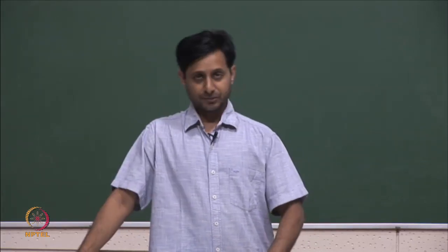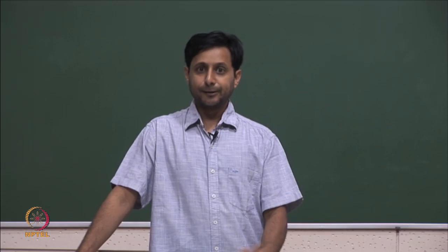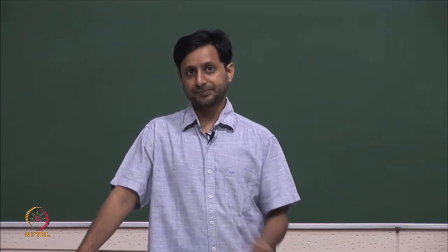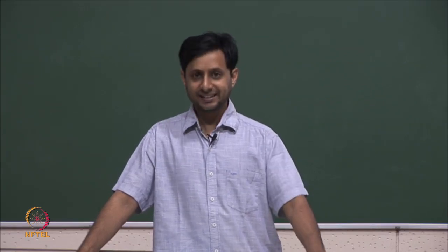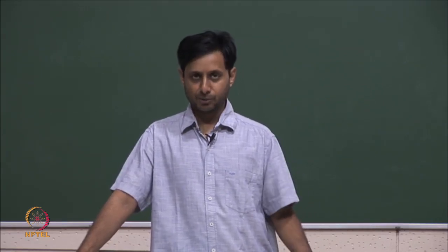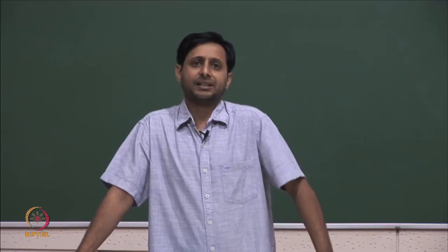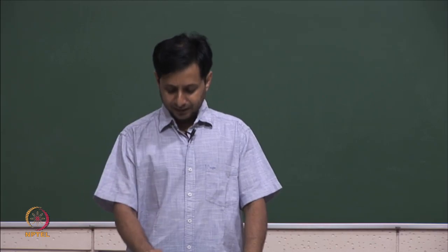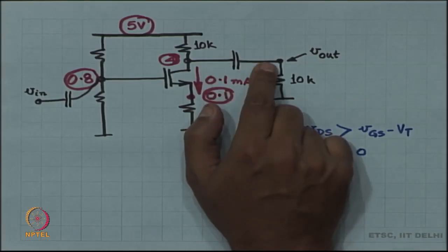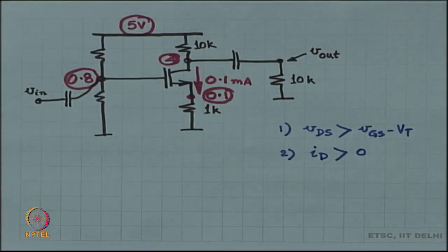Absolute means the sum of the DC operating point and the small signal, the incremental signal. Just by the way, the incremental signal need not be small all the time. For small signal analysis to be valid, it has to be small, but otherwise it is just an incremental signal, and the incremental portion always goes through the capacitor as a short circuit. So, small or large, it really does not matter.